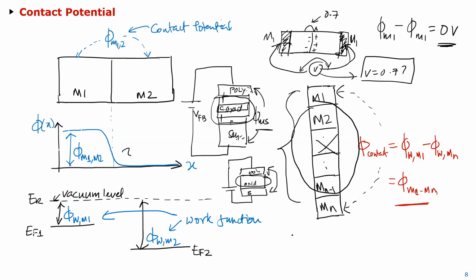Yeah. So just trying to understand, oxide is going to work as a dielectric in this particular case. Usually we add multiple layers of dielectric to reduce the effective dielectric constant, and that changes the capacitance. But from this theory, it looks to me that even if I change the dielectric constant, that's not going to affect my capacitance. No, no. I think the capacitance still changes.